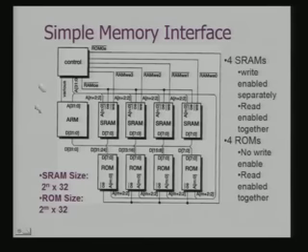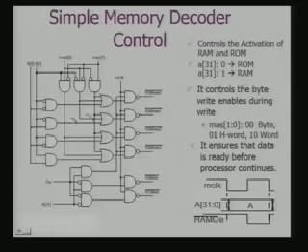Now, the next question is, how do you design this control? When I am designing this control, I have to use various control signals which this ARM core is producing, and those control signals have to be used. This is a simple example of a control signal. This control can be implemented on an FPGA or in terms of discrete logic.